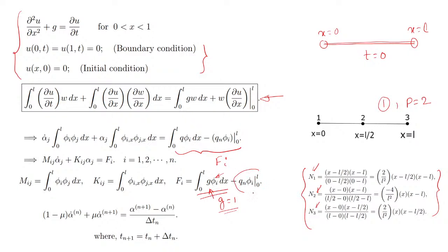And if you look at the second term, for this problem the second term is 0, because at x equal to 0 and at x equal to L, at both the ends temperature is specified. And we said that in a given problem, when your primary variable is defined at the boundary, your weight function has to be 0. So in that way this term is 0 for the problem in hand. But in a practical case, obviously there will be certain non-zero terms.